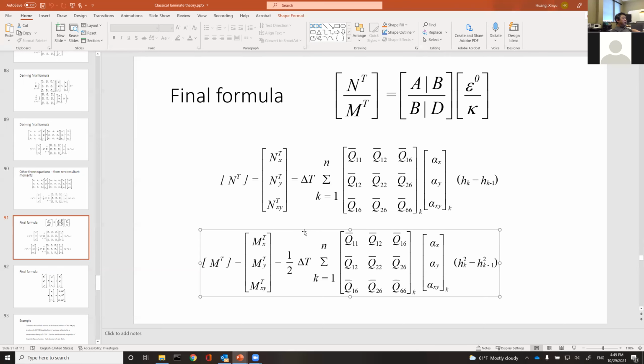So in order to calculate hygrothermal stress, you have to know the change in temperature from your stress-free temperature. Stress-free temperature is a reference temperature. People assume at that condition there's no thermal stress and everything is in its most free state.